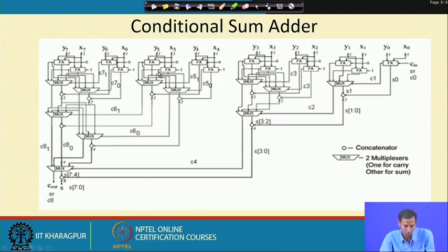So, from this group whatever carry is generated will affect this. And then if I consider these 4 as a group, the carry generated from these 4 will come into effect at this final multiplexer stage. Okay. So, if I concatenate 1 and 1, then I will get 2.